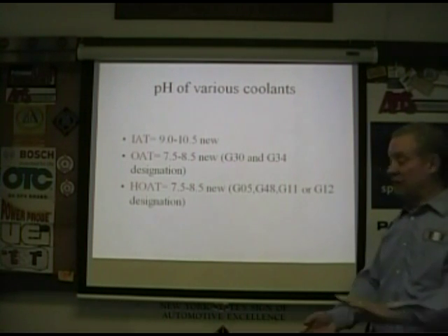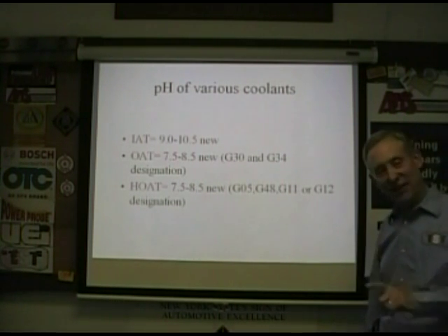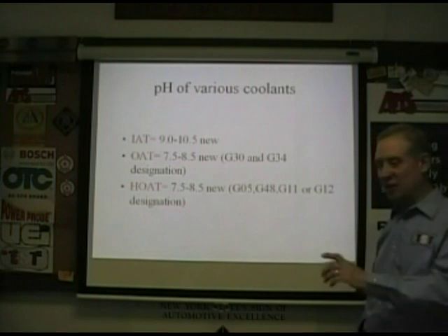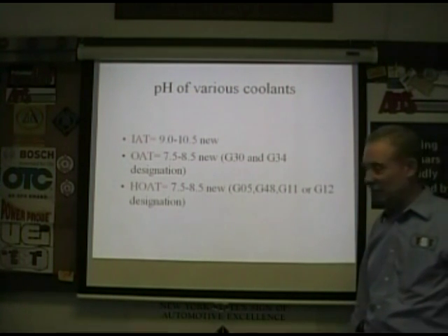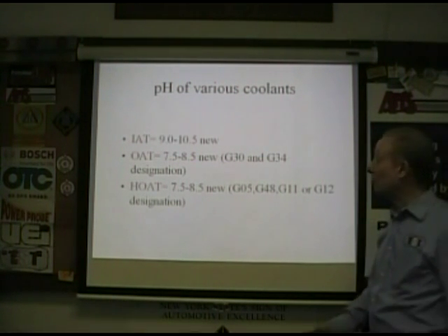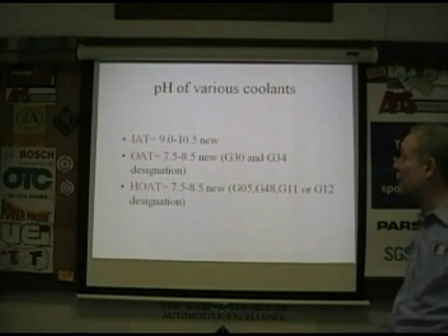And if in doubt, saying it again, if you don't know what's in the system, flush it. Make sure it's clear water all the way through, clean, clean, clean, and then fill it with the right stuff. Make sure it meets your manufacturer's spec.